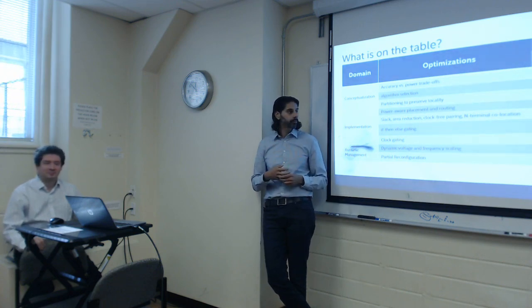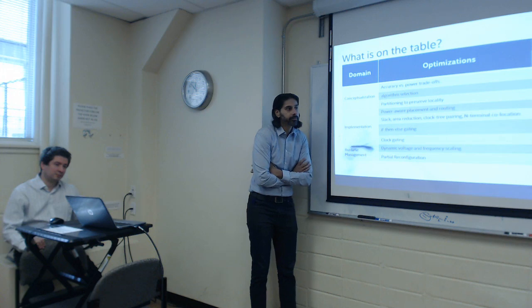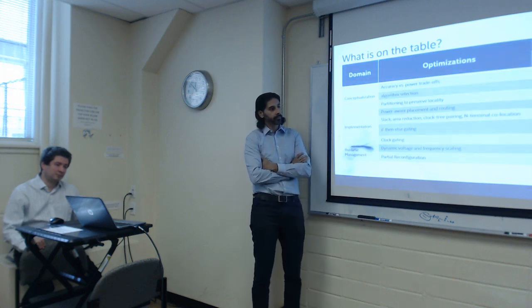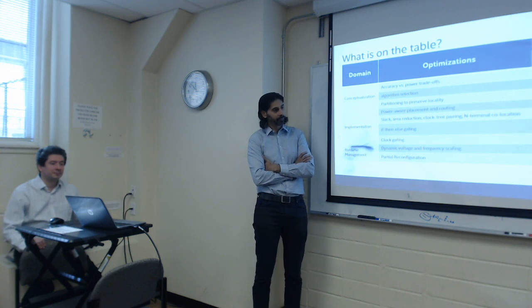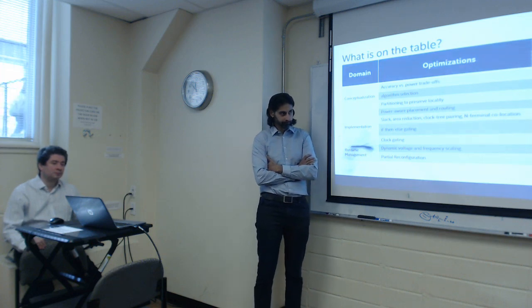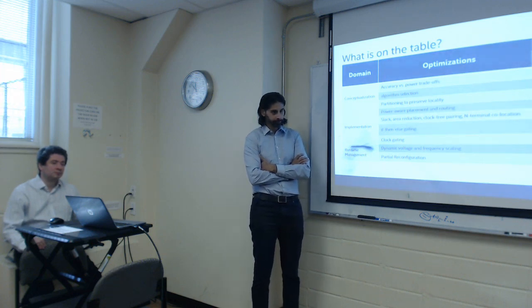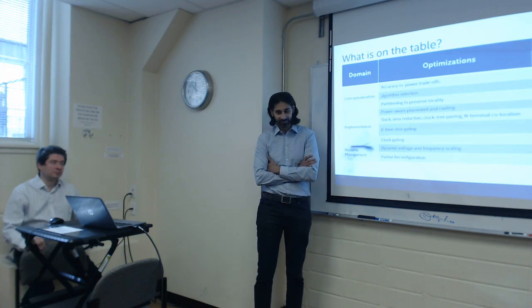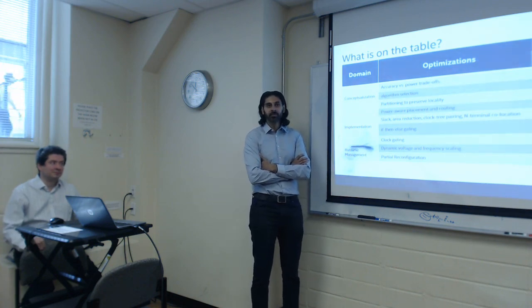Just in the planar process technology, you had the body bias that you could use for reducing leakage, and you had the high-speed, low-power concept in some previous Altera families, but I guess with FinFETs, the body bias option is not there. Could you comment on the static power ratio that you're seeing in the FinFET Stratix 10 versus traditional planar CMOS?